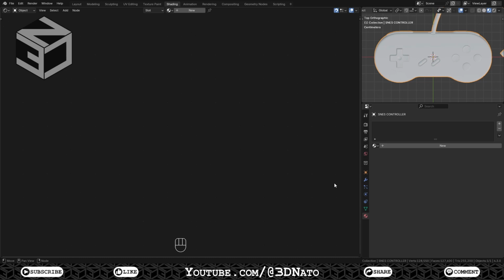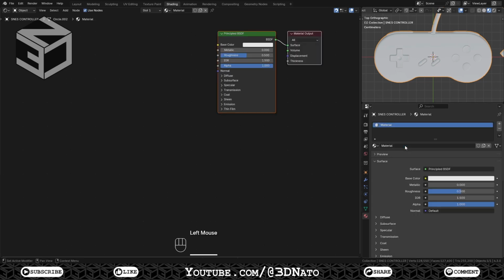With the controller mesh selected, go to Material, click on New to create a new material, and rename it Controller. Now let's start adding some nodes in the shader editor window. We're going to use 7 nodes here.